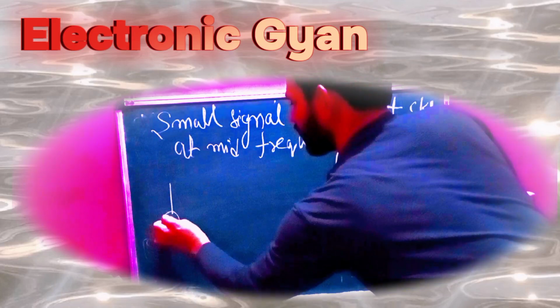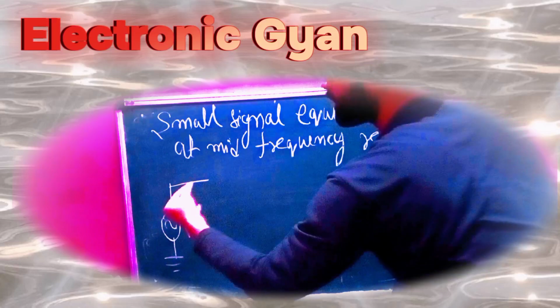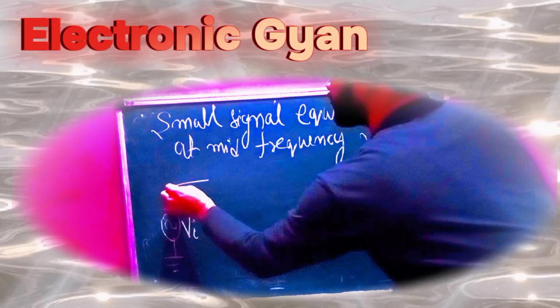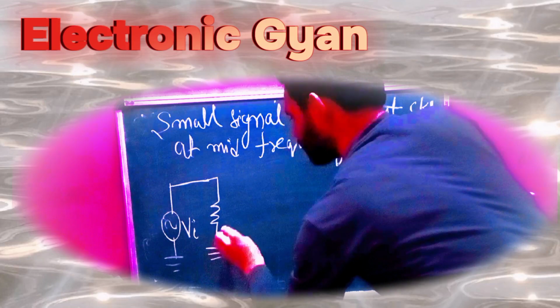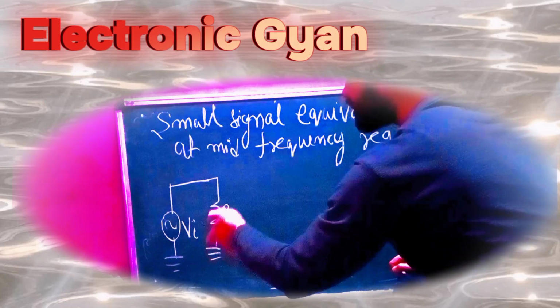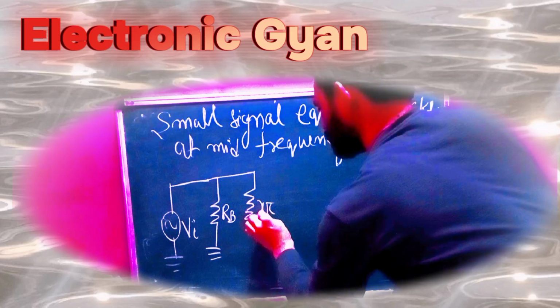First, this is my small signal input Vi, which we can call a perturbation, a very small signal in the range of millivolts. It gets coupled through to the transistor amplifier, and here is my base resistance, which is the parallel combination of the bias resistance and the AC resistance, r pi, of the transistor.